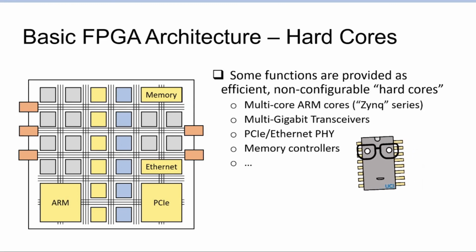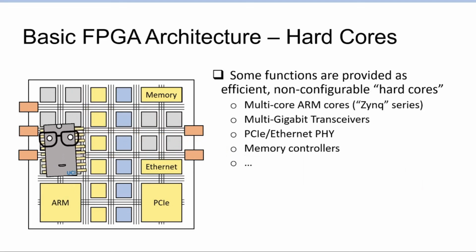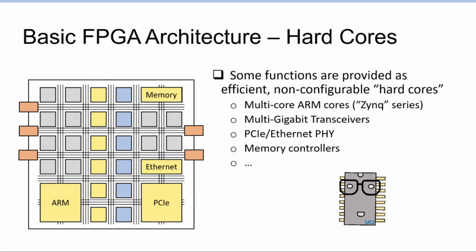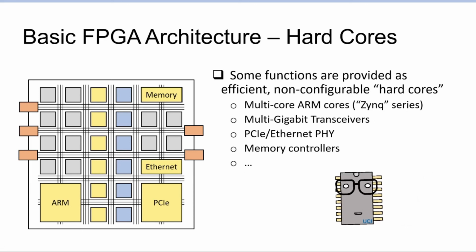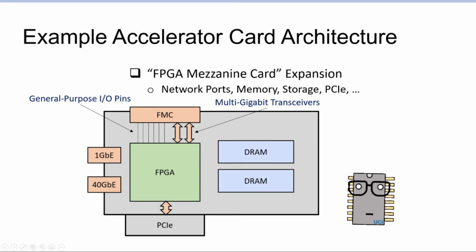And we try to make use of all these resources by writing programs that configure all these programmable CLBs to implement any functionality that we want. Another benefit of buying an off-the-shelf FPGA as opposed to trying to spin your own ASIC is that the surrounding infrastructure in terms of PCBs, wiring, memory, and things like that, there are offerings for those things that are available already.